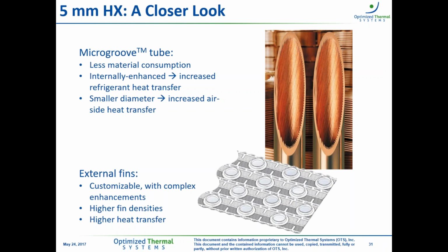And we see the same types of things with the fins. We have the ability to implement a number of different enhancements on the air side on these fins. With smaller diameter tubes, we see higher fin densities, and we see higher heat transfer coefficients on the air side as well.